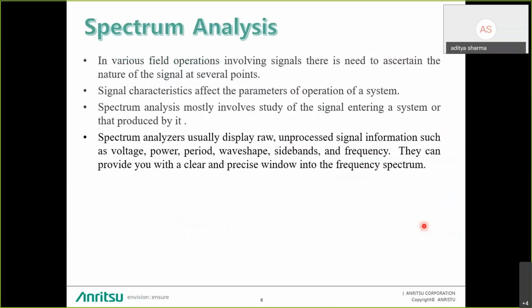Now the question is, what is the need of a spectrum analyzer? Like I told you before, a spectrum analyzer is used to check the harmonics of a signal, the different spectral components, the harmonic components which are available in the signals. For that, you need to use a spectrum analyzer. Along with that, if you want to analyze a modulated signal, or do the demodulation of a modulated signal or banded signal, at that point of time you also need a spectrum analyzer, because you won't be able to do all those functions using a simple oscilloscope.